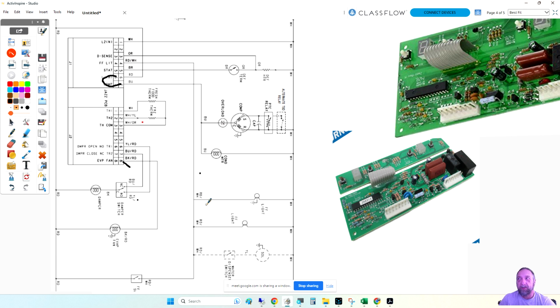This is a trick, Daniel. Look at it closely, because I heard what you said earlier, but anybody else see it? Look closely, guys. How am I going to get that evaporator fan to run? I'm going to run a wire from that J2 pin 8 right here, but I have to complete the circuit for the fan. What do I need to complete? Goes to the red wire. It goes to what? It shows the red wire in the breakdown. It can't go to red, because look, this red is also coming into the fan already. You can't put 2 reds there, right? So what do I need?